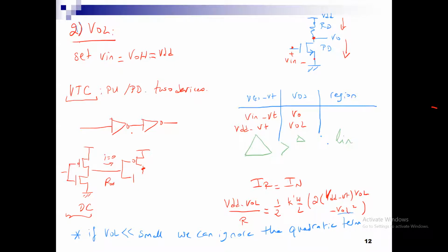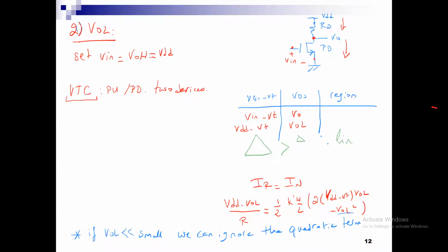Now in the delay analysis, I will have a capacitor on the output representing the load of the next stage. In the delay, I will have a capacitive load from the next stage that can affect me. For your purposes, we tell you what C load is for 311. Okay, excellent. Now let us take a look at the slides and then continue deriving the other quantities.